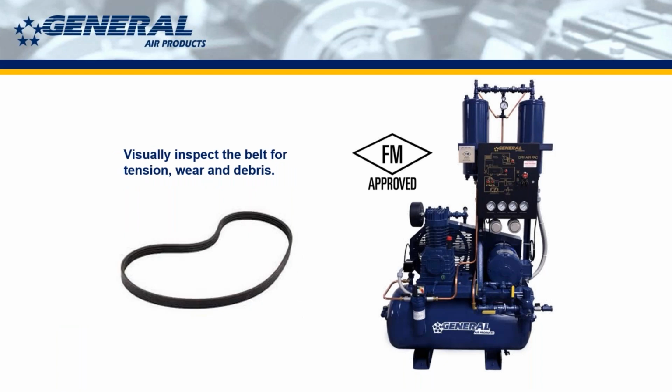You also want to take a look at the belt for any tension and wear. That's, again, a standard part of lubricated tank-mounted maintenance procedures, is checking that belt. And what we mean by there is debris. Like if it starts to get misaligned, the belt starts rubbing against the flywheel, and you start to see little bits of powder, black powder, that collect on the pan or on the floor underneath of the unit. And if you start to see that, that means that things are getting misaligned, which means the pump and the motor might be getting loose and they're not lined up properly, so they need to be retorqued. And then you'll probably need to get a new belt at that point too. We carry our belts for a long time, so the belts are really easy to get.